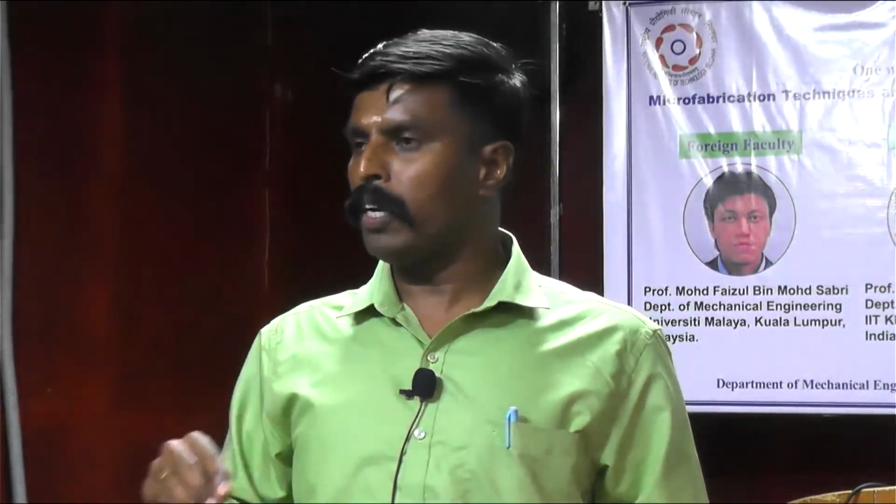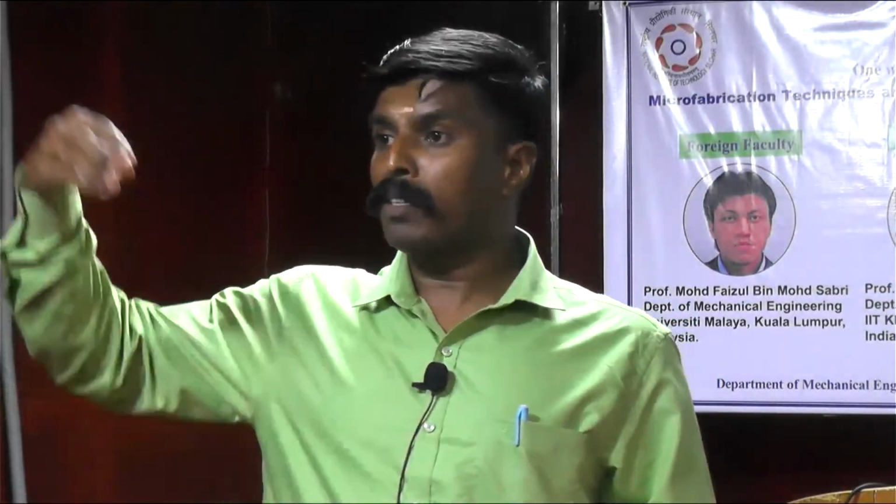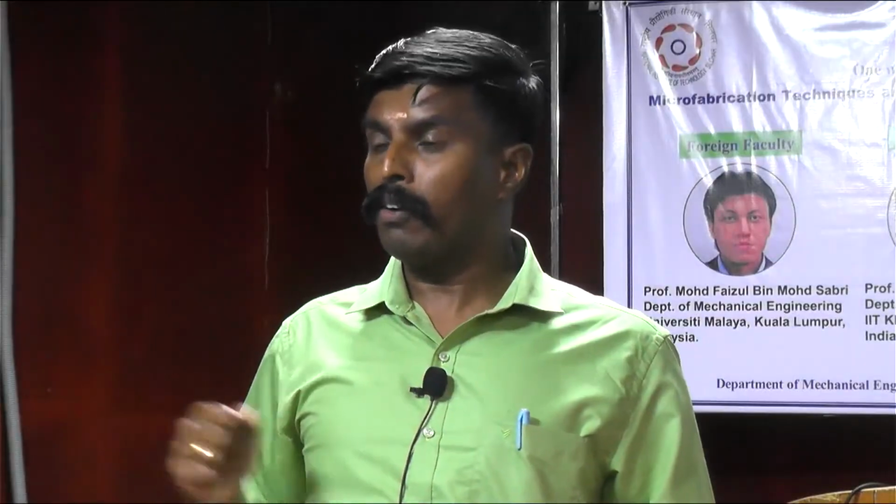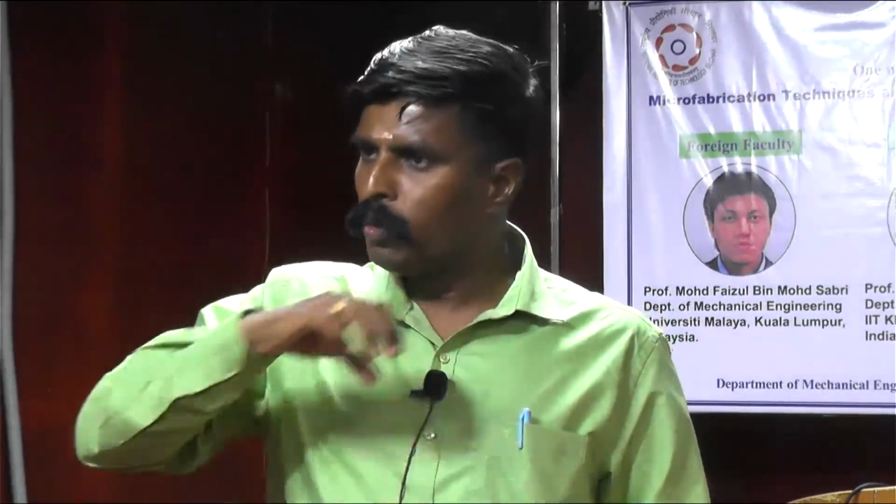Otherwise, for 10 mm thickness in one pass, people search for EB welding only, electron beam welding. But with the advancement in TIG welding, with the help of ATIG welding, without preparing the groove, autogenous welding itself we can do. That way it is manageable.